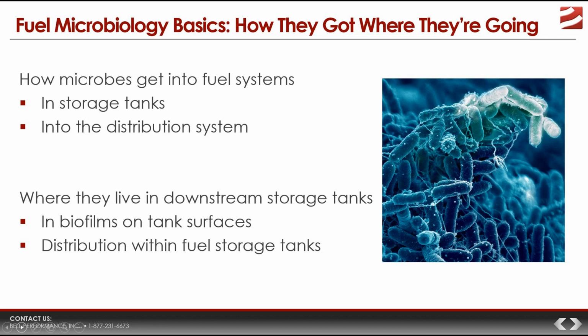So in these tanks, where do microbes live in these kinds of storage tanks and fuel systems? Well, when we talk about microbes in storage tanks, we are accustomed to talking about how microbes like to live at the interface between the fuel and the water. But most commonly, though, that's not their favorite place. Their preferred place, I should say, is that they grow best within biofilms that are located on solid surfaces.